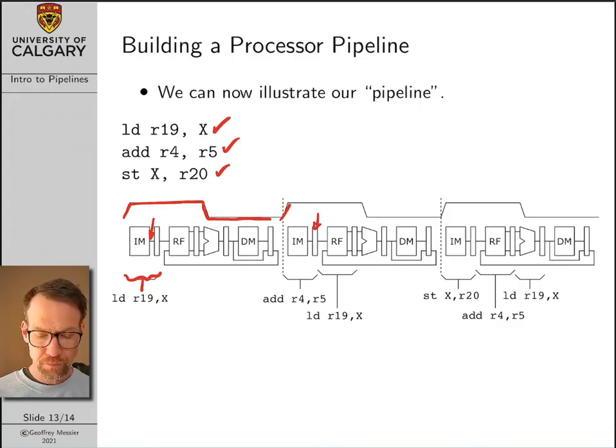And so once this result is locked in place, then the instruction can proceed into the register file stage, and we can read the values from our register file, and that just goes as normal. However, now that we've locked our machine language instruction in place, the instruction memory isn't really doing anything anymore, right?